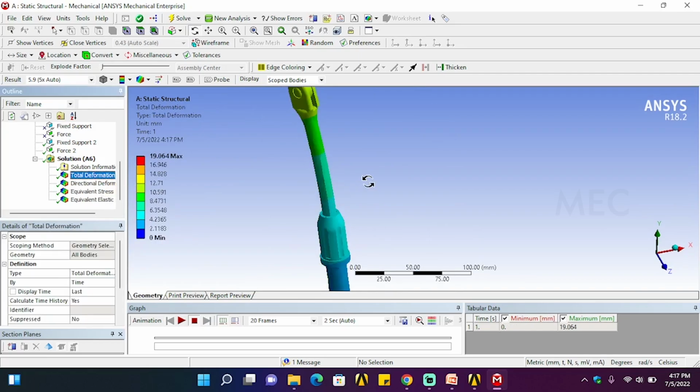Based on the results, you again have to calculate the factor of safety value, and it should be greater than 1. After that, you can do the drawing, modeling and 2D drawings, and go to manufacturing. Finally you again arrive at this particular shape of the product, but the strength and stiffness are greater as compared to the existing component.